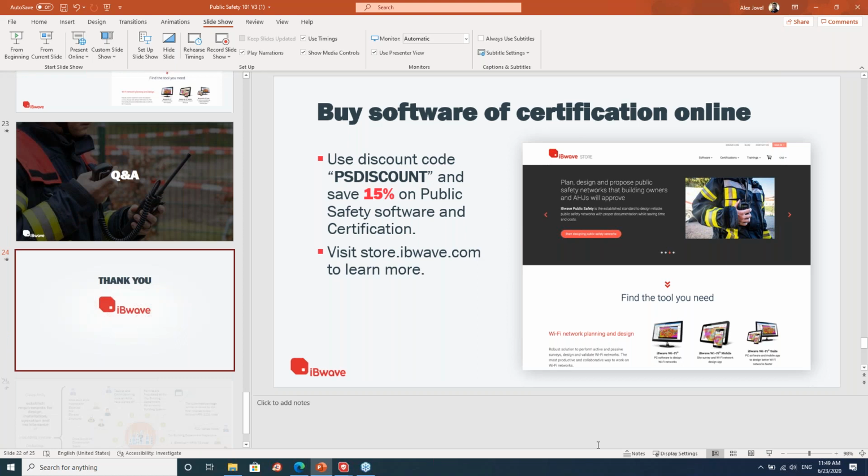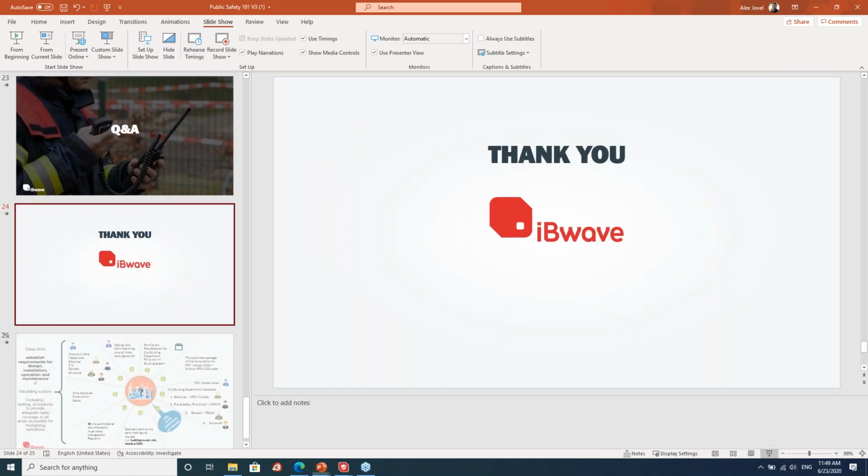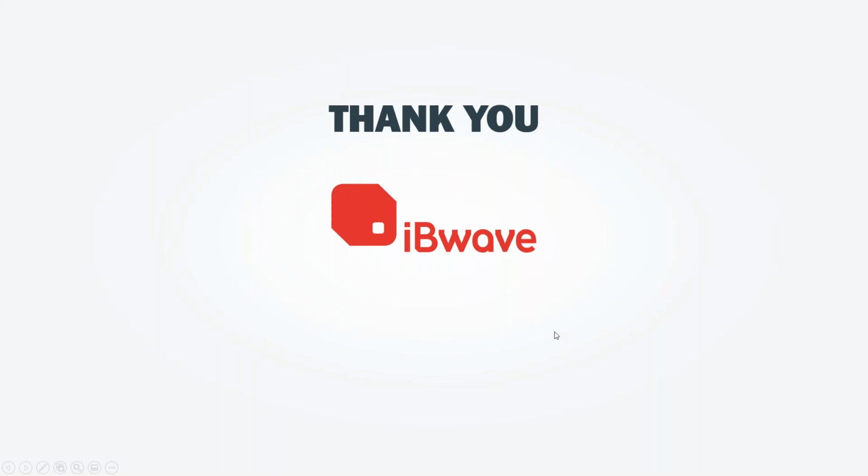Okay, thank you. Maybe two more questions before we end the session. A question from Adam: is there any particular reason why you would install the repeater so far from the donor antenna, reducing the SNR? I mean, it's going to depend on the type of building. Yeah, I guess in theory, if you want to decrease that cable between your donor and repeater, you could put one close to it.